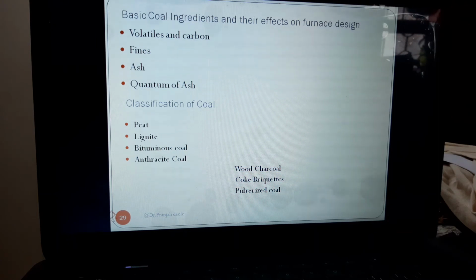Its appearance is brown and it contains high ash and low heating value. It is a low grade fuel having a calorific value of 21,000 kilojoule per kg, and it is too brittle and hence it is converted into briquettes, which can be easily handled. It burns with heavy smoke. There are comparatively large deposits of lignite in Kashmir, then Neyveli and Rajasthan. This Neyveli power plant actually uses this type of fuel.